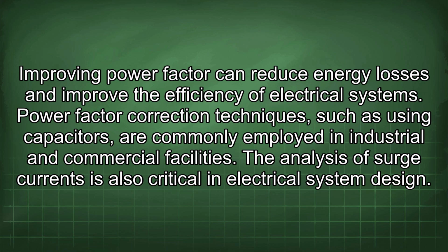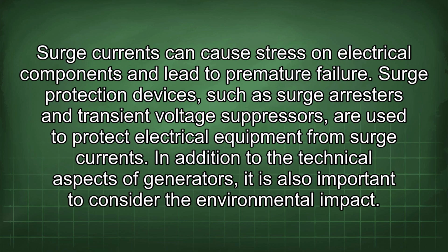The analysis of surge currents is also critical in electrical system design. Surge currents can cause stress on electrical components and lead to premature failure. Surge protection devices, such as surge arresters and transient voltage suppressors, are used to protect electrical equipment from surge currents.